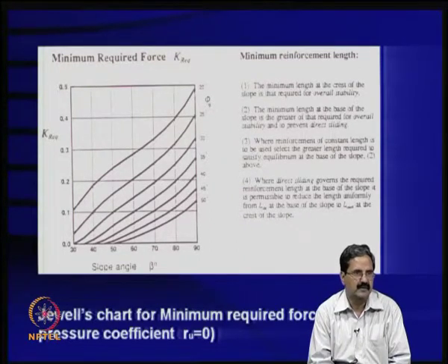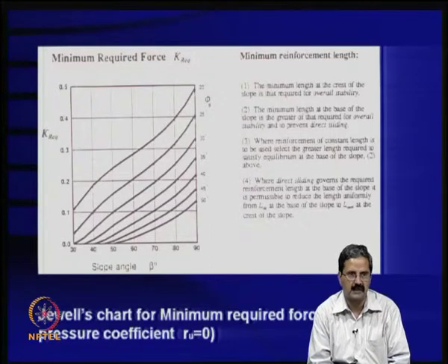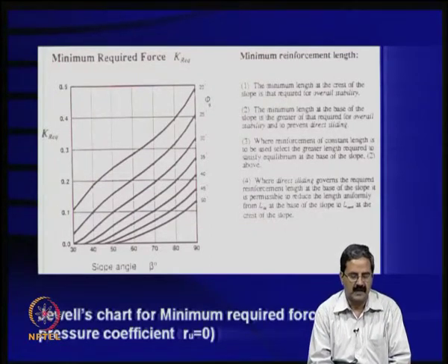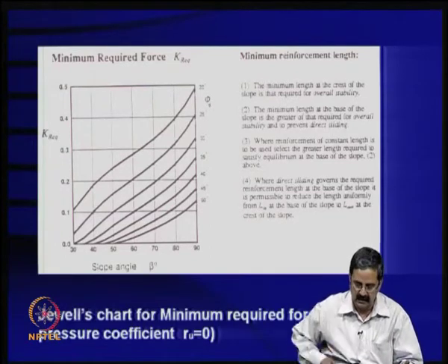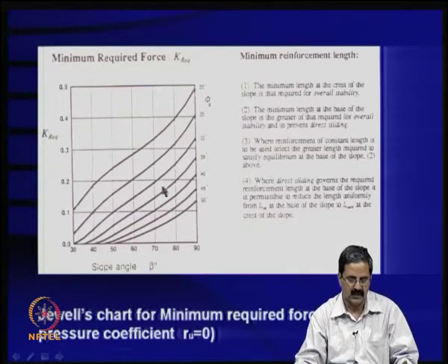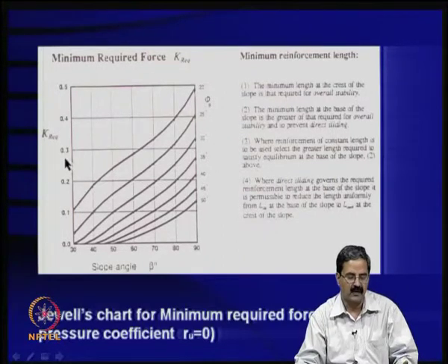like 1 minus sin phi by 1 plus sin phi, something like that. And if you know the inclination, it can be found out. And if there is an earthquake that comes, one can even calculate the dynamic earth pressure increment also. So, this concept is very important in terms of understanding what is the required